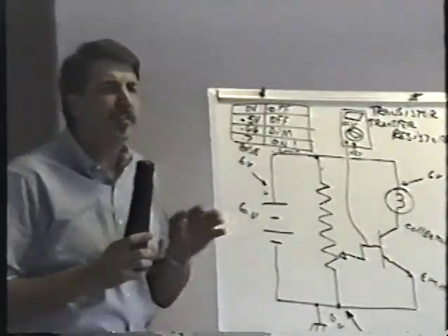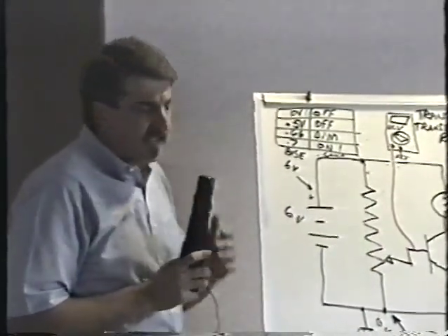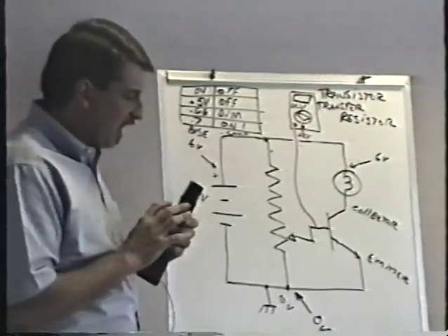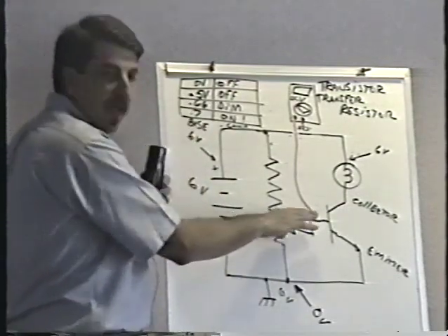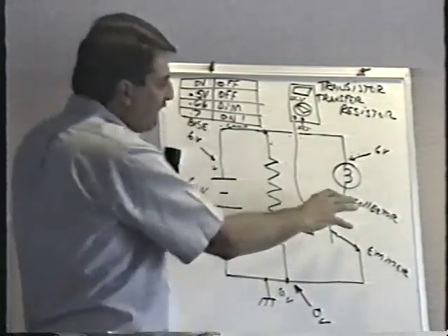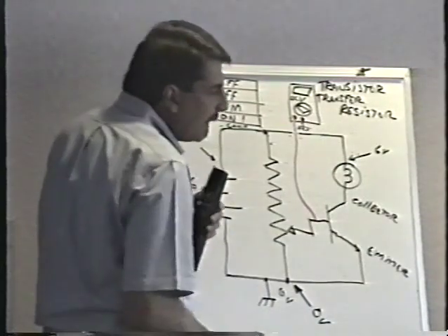You know how a transistor is referred to as an amplifier? It's not like the transistor takes a signal in and amplifies it and spits it out. All they're talking about is this, that an itty-bitty tiny change on the base, in this case just this 0.04 of a volt, can make the difference between something being, let's say, just partially on and completely on.